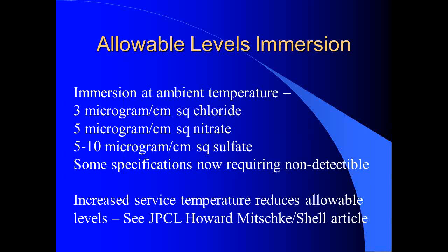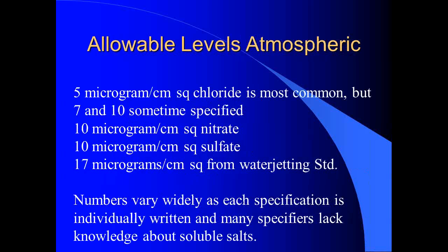As soon as they got up to temperatures of, say, 120 degrees, the allowable level dropped from 3 to 2. Anything over 2, they would fail. If he went up to 150 degrees, it was reduced further down to 1. If they had 2, it failed. By the time they got to 180 degrees Fahrenheit, if there were any salts measurable at all, they failed. They had to be down to non-detectable. Not non-detectable in a laboratory, but non-detectable with a standard field test kit.